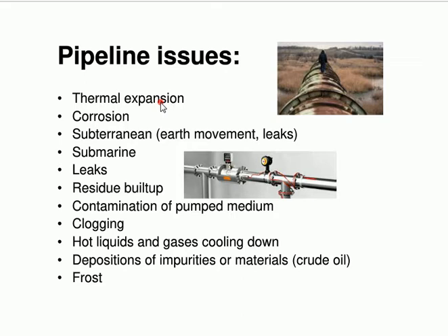So what's happening is they put some bends in the pipeline to pick up the stretch or the thermal expansion of the pipeline. So every couple of miles you've got some sort of U-bend in there to pick up any expansion and to deal with that. Problem is, whenever you've got a bend, you've got a problem with deposition of materials. So stuff can get stuck in the bends.